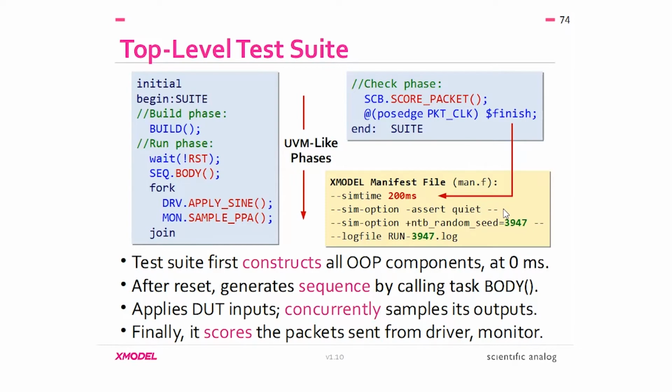Then per our guideline number 10, we're reducing the verbosity of the assertions we incorporated in this test bench by telling the simulator to be quiet. We rely on the pass and fail display tasks to tell us what happened with the assertion. We can also use a runtime option to generate a random seed that'll govern all of the $randomize calls.